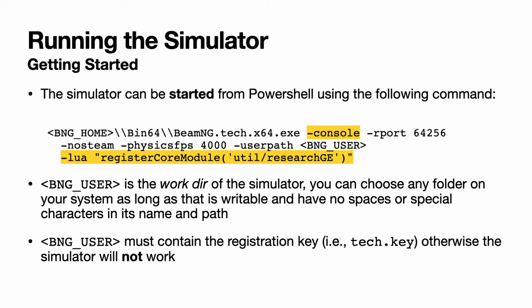Here you see that BeamNG user is the working directory, so it must be a directory on your system where BeamNG will store its cache and temporary information and all the files that it needs to work correctly. As I said before, under this BeamNG_user folder, this working directory, you must place the tech key, which is basically how the simulator verifies that you have been registered to the program.